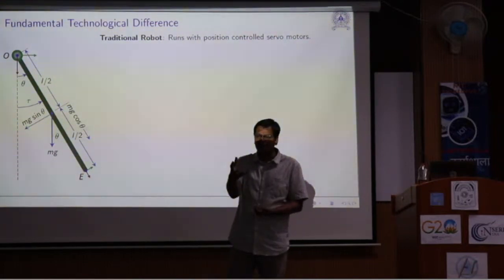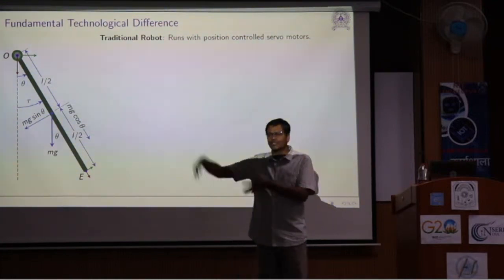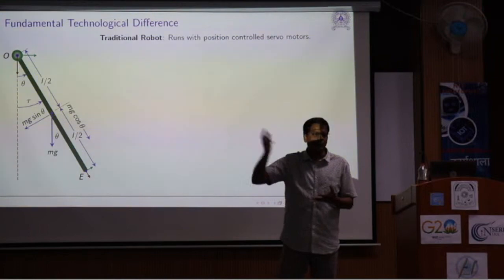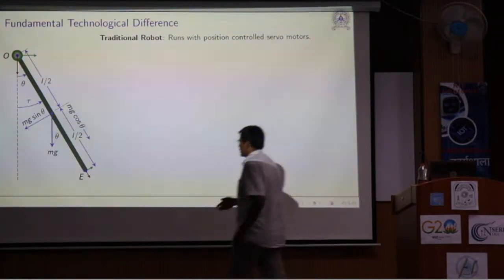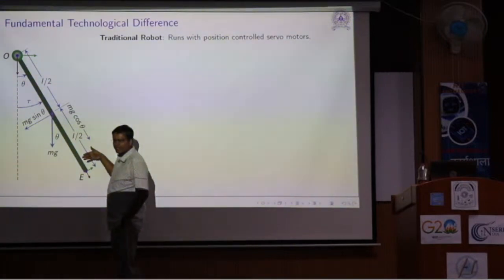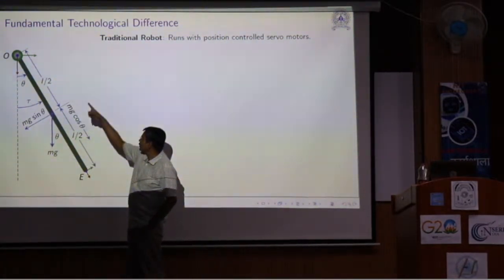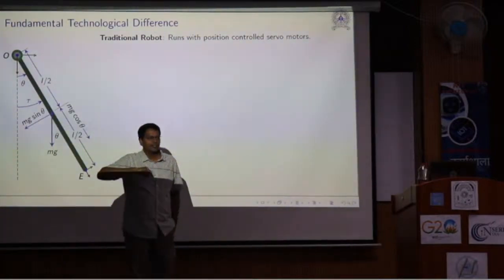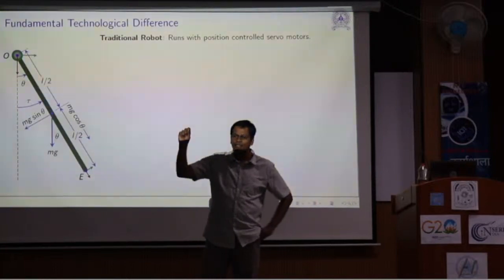If that torque generating actuator is very, very powerful, like a 250 kg payload robot, you can imagine how much torque it can apply. So if it meets any kind of obstacle in between, it will break it, because it runs purely on the feedback of the joint angle. It tries to servo to the commanded joint angles.